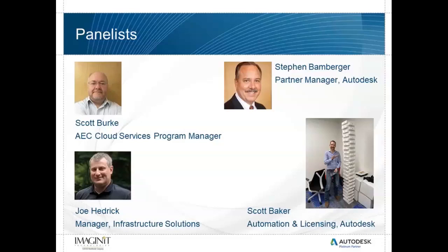All right. Michelle asks, we have some users who are using Civil 3D. What's the recommended way to get our standards to home users? Should we have them copy the standards to their C drive? Any advice for anyone using ProjectWise and getting standards into their system? So you could do that a couple different ways. One way would be to have them put it on their C drive. Another way would be to share it through BIM360 docs and just put a folder out there that people could grab that standard Civil 3D template from.